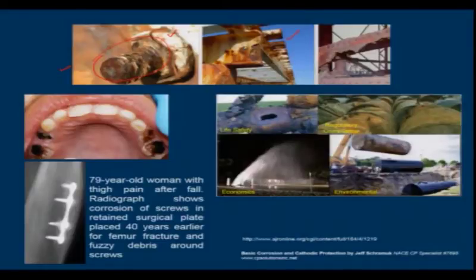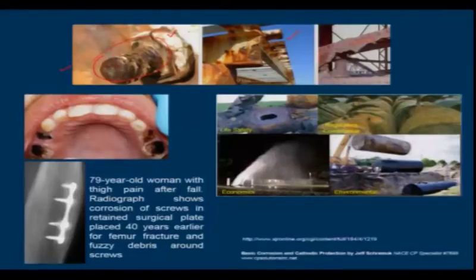Corrosion in most cases comes with a different color, and in many cases you do not find any signature of corrosion, but still it happens, and those cases are more deadly than cases where you have a signature in the form of color change. Here you have the red rust which is forming, which is a typical feature of iron corrosion. These are hydrated ferric oxide, containing ferrous or ferric ions, and this happens because of reaction with oxygen and moisture in the environment. This is basically atmospheric corrosion.